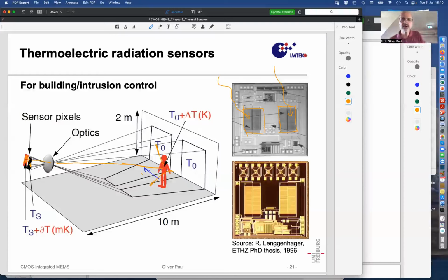These detector elements here are thin membranes etched from the back of the silicon chip to produce a thin membrane made only of the dielectric materials of the CMOS process. And integrated in those thin membranes are little pieces of polysilicon and aluminum, or polysilicon of N-type and P-type, that constitute the temperature sensor.